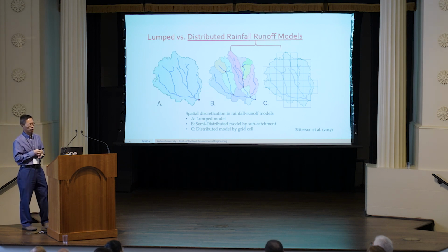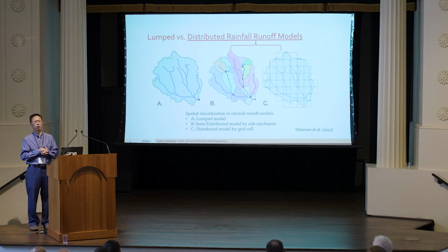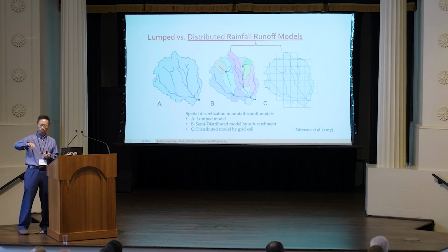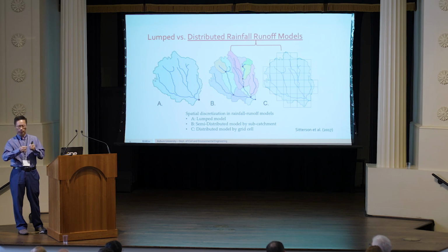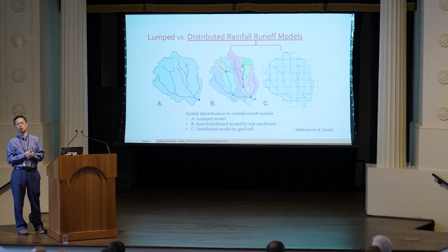So, the USGS StreamStats has been implemented in almost all 50 states, maybe only 1 or 2 left. If you use StreamStats, you zoom into your road system where you want to put a bridge or road crossing, and select that point as the outlet. Then they do the watershed delineation, and determine the area, maybe slope, or maybe stream length.